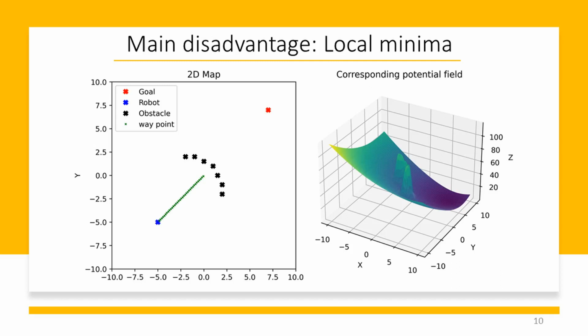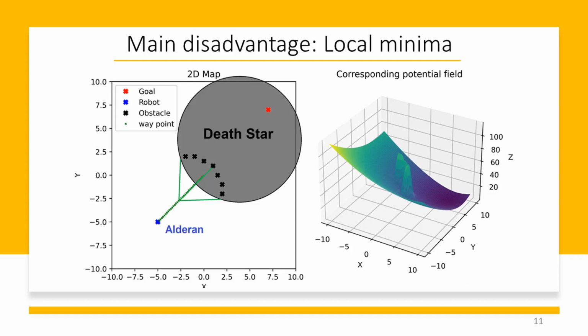When the rover drives into a local minimum and checks its surrounding potentials and registers that they are all higher than the potential it is currently on, it will think it reached its goal, which is obviously not the case. So remember, there are obstacle configurations that create local minima, and they are very deadly for path planning when using potential fields.